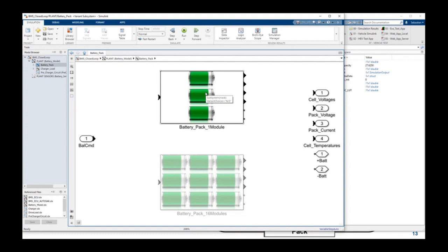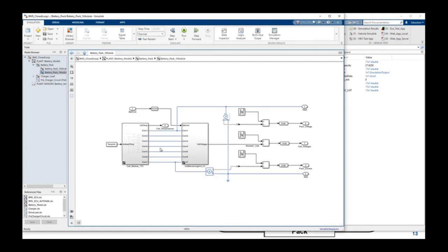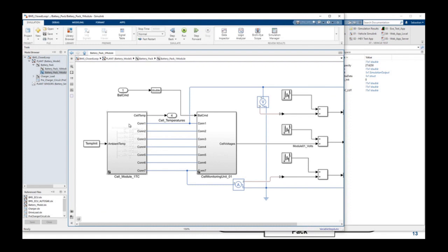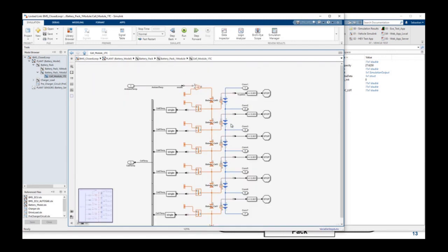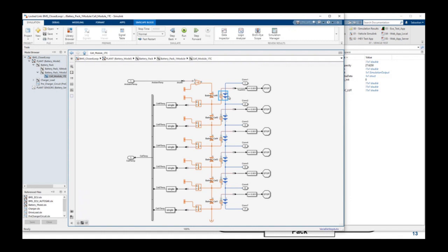So one, that means that we have created a model of one battery cell, and then we will replicate it 6 times, because before we have seen the 6 switches. So here, if I go in the subsystem that is on the left-hand side, we can see that we have the 6 batteries. Here, you see, we are retrieving our model of one battery. And in blue, as I mentioned, that's the electrical domain. But you also have now in orange the thermal domain that is modeled. So now I am also taking into account the thermal behavior of my battery. And you can see that we have 6 batteries. So at the end, more or less, the default voltage of one battery is around 4 volts. So if we have 6 batteries together, at the end, we will have 24 volts output, more or less. Okay.